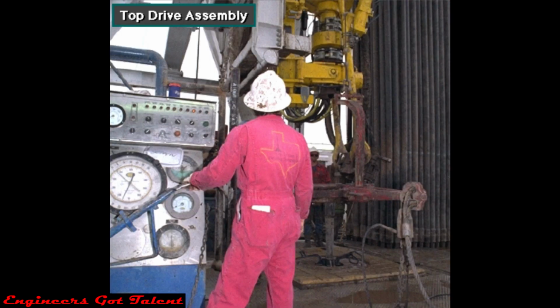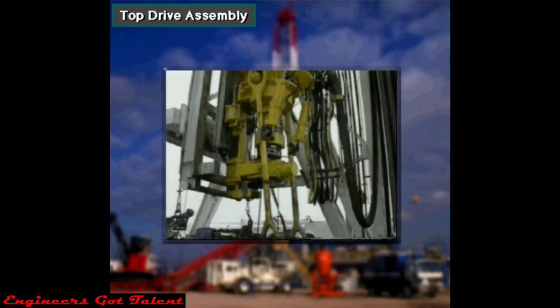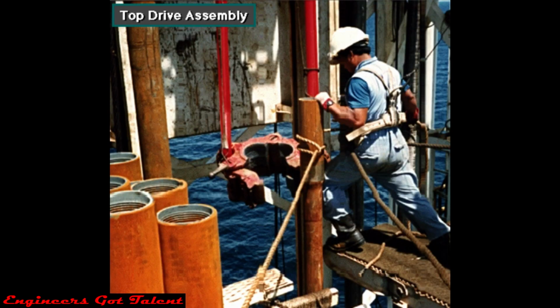The driller controls the top drive's operation from the console. The pipe handler assembly also includes links, an elevator, and an automated link tilt assembly. The driller activates the link tilt assembly to position the links and elevator at the mouse hole for picking up or laying down drill pipe. The link tilt assembly also assists the derrickman in racking stands.